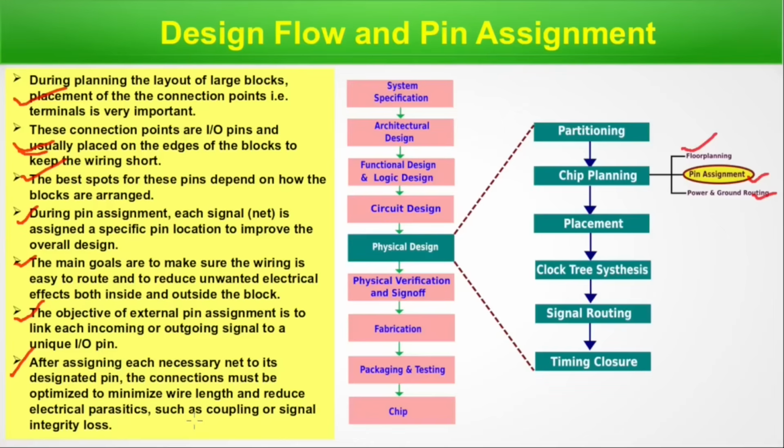And later on, we will see that each and every device in a chip, each and every device within a block, requires power and ground. Otherwise, they are not electrically connected. They are isolated. So every component has to get connected electrically. For that, they must get connection to power and ground. So power and ground is the primary connection.